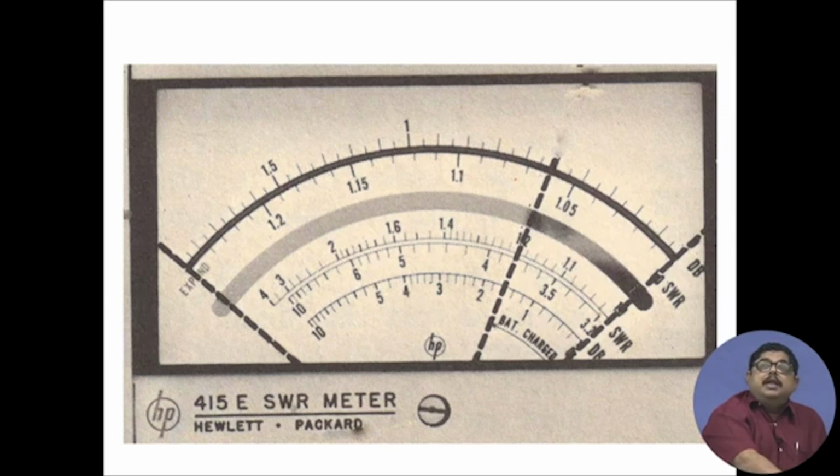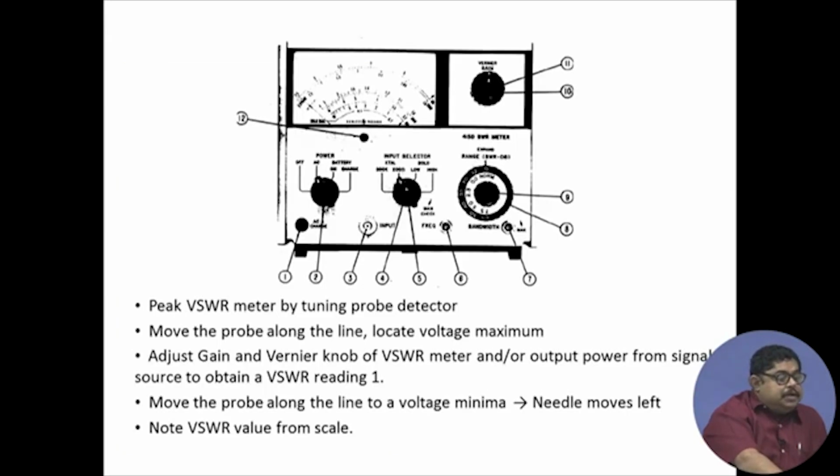So, from here you can measure that. So, this instrument helps you to measure VSWR. What you do, again I am repeating the procedure: pick the VSWR meter by tuning your probe, move the probe along the line, locate the voltage maximum,